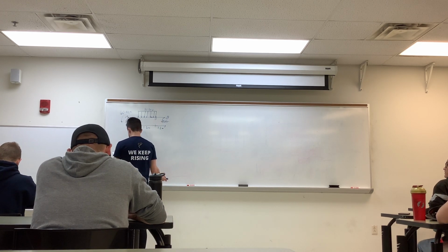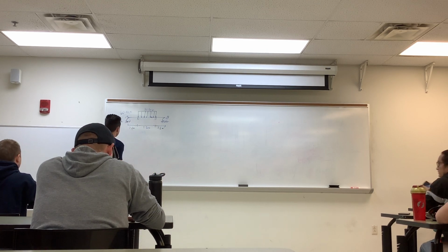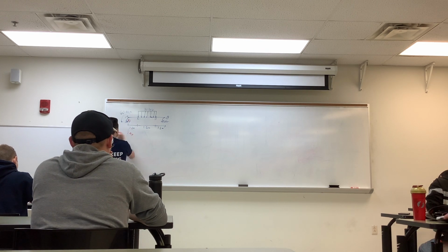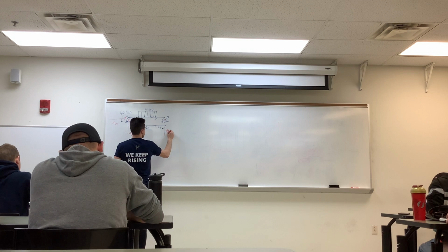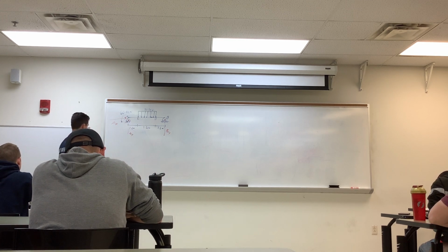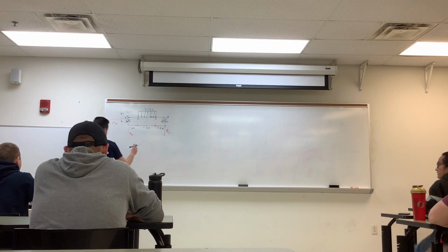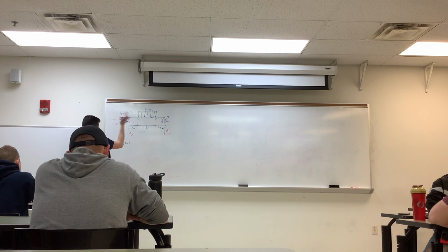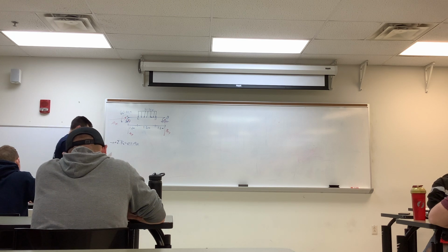So we have our reaction forces at A, so we have AY, AX here, and then BY. The first one is relatively easy. We can just sum forces in the x direction, with right as positive, equal to 0. We only have this AX force in that direction.